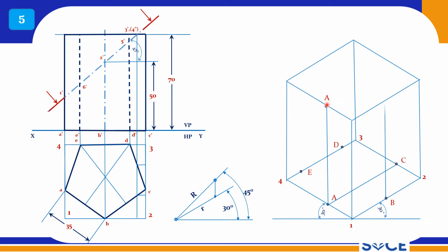From the A to A line you mark 1. So on the B line you mark 2. So this vertical distance should be measured here, that is converted here, and that converted distance should be marked here. So 2 and point 3, you draw this rectangle here, and from the intersecting point you measure this height. So this height is 70 mm actually, so that should be converted and that height should be used. So this is point number 3. Point number 3 and point number 4 can be obtained in similar fashion, and 5, 6, totally 6 points.